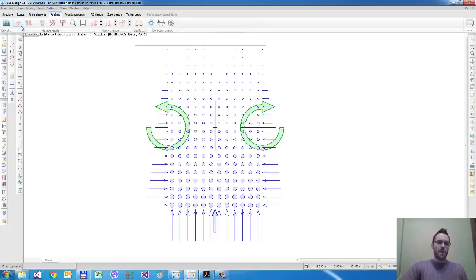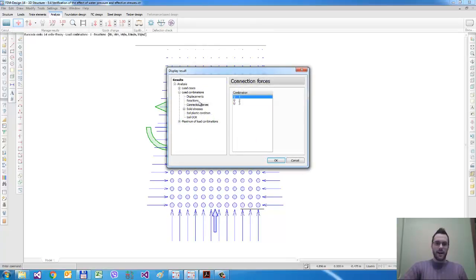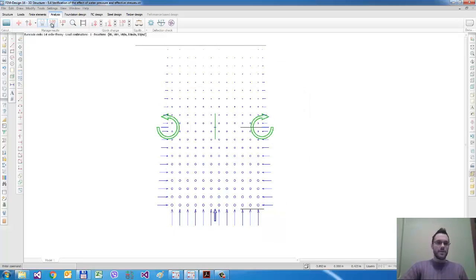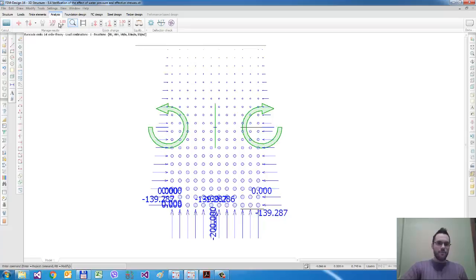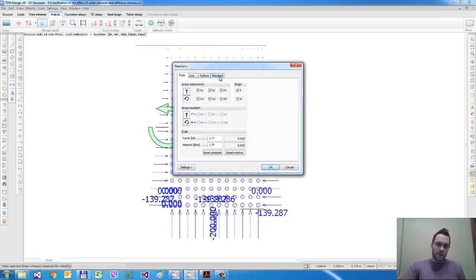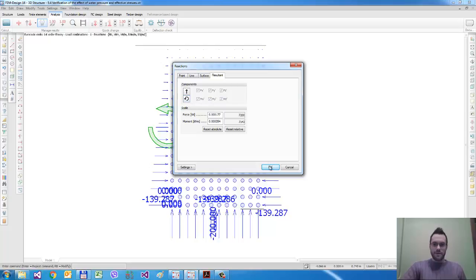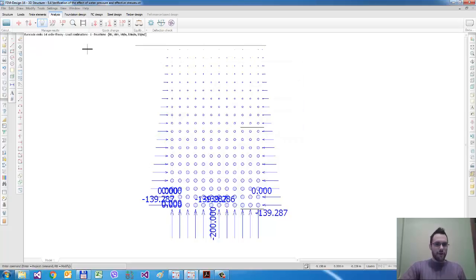So in this case, if I run the nonlinear calculation and check the different reaction forces at the wall, I can see, with the automatic min-max value, that at the side wall, if I just show the distribution of the forces, not the resultant, for groundwater level 1 we have 140 kPa reaction at the side wall.